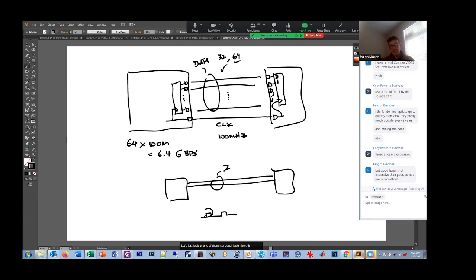And if it's representing a 1, it'll clock one way. And if it's representing a 0, it'll not clock. But inside this, there's a signal. You force the signal to toggle every so often. You can encode the signal so that it's always got a transition at some time or another. And on the other side here, coming out of here, we have a clock and data recovery circuit, a CDR.